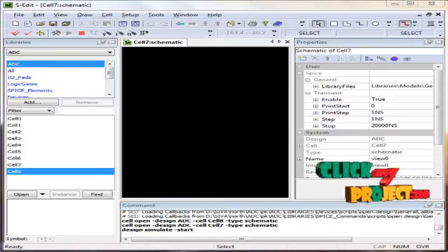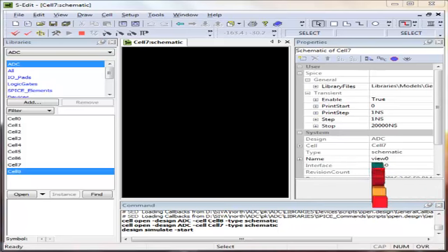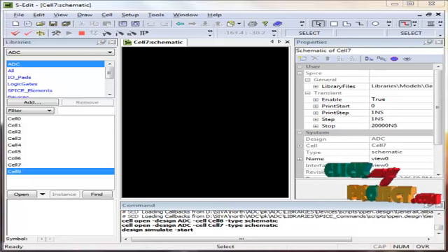Analog input voltage Vin is held on a sample and hold device. The SAR ADC architecture implements the binary search. The n-bit code register in the SAR logic block is first set to mid-scale. Then the comparator performs a comparison between Vin and VDAC. If Vin is greater than VDAC, the comparator output is a logic high and the MSB of the n-bit code register remains at logic 1.